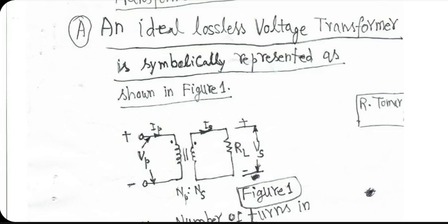Last time I had shown you a PPT where we discussed a bit about the losses also. Losses are primarily coming from two different things. One of them is the fact that wires used in coils have finite electrical conductivity that generates the so-called conductor losses. And the second factor is the core's magnetic material's imperfect behavior.